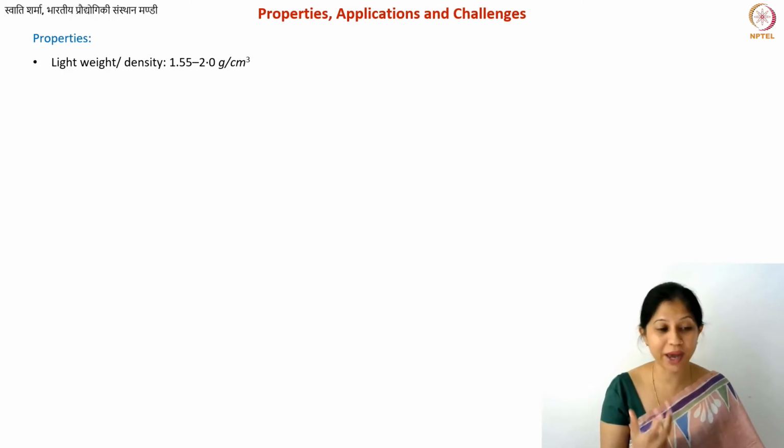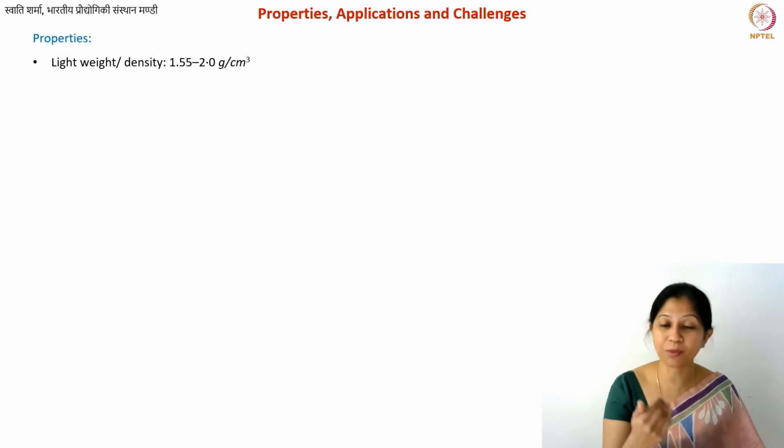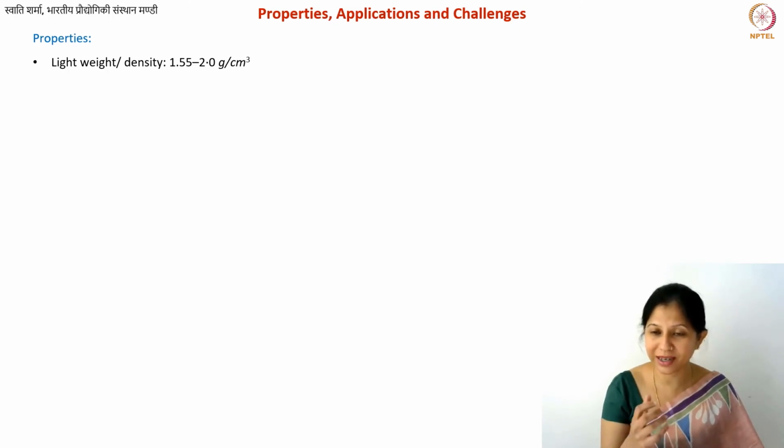What would you expect from something that contains carbon fibers and a relatively disordered carbon matrix? Because it is disordered, it may have some curved structures. It will not have the density of graphite for sure. It is not a polycrystalline material. You may even have turbostratic carbon fibers. So your density has to be lower than that of graphite, but it is more than that of glass-like carbon,